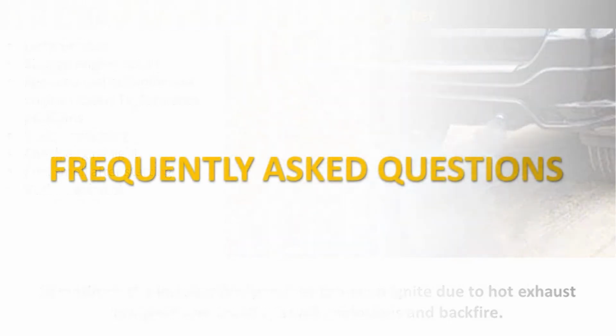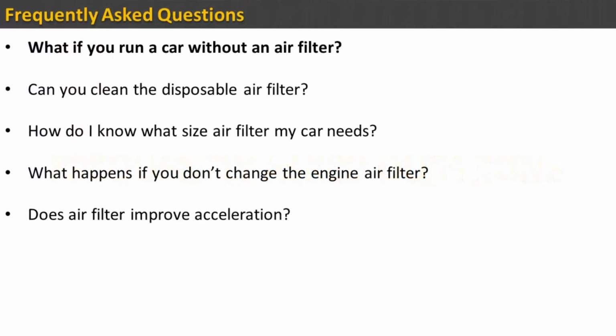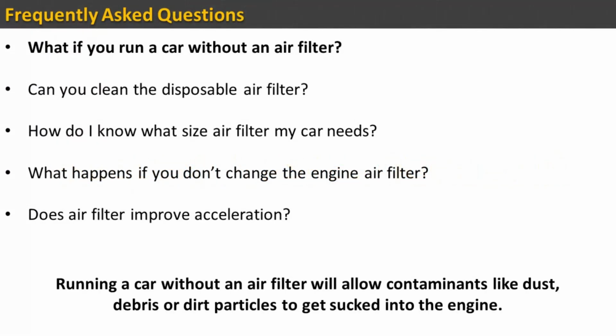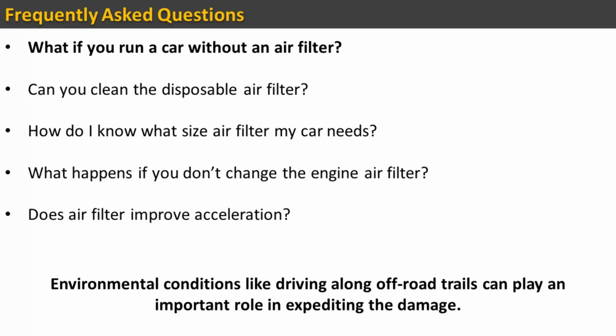Frequently asked questions. What if you run a car without an air filter? Running a car without an air filter will allow contaminants like dust, debris, or dirt particles to get sucked into the engine. This can potentially damage the engine components, including pistons and cylinder walls, and negatively impact the overall engine performance. Environmental conditions like driving along off-road trails can play an important role in expediting the damage.